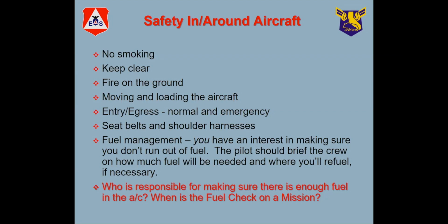Staying on the keep clear thing, it's very important to consider the propeller a lethal instrument of death. Do not get in the arc of the propeller, even if the engine is cold, but particularly if it's been run in the last hour or so. For various reasons, you could have an engine crank off independently, and it doesn't happen often, but it's not a pretty sight if it happens.